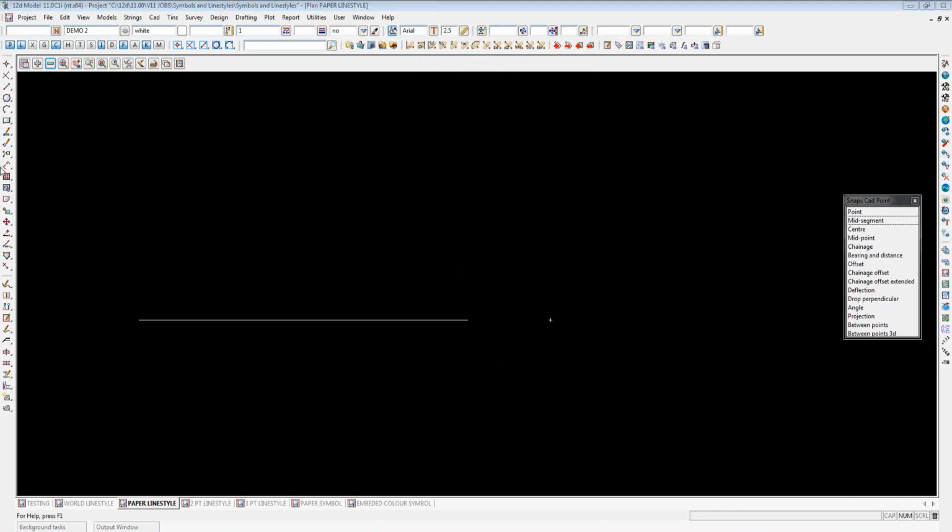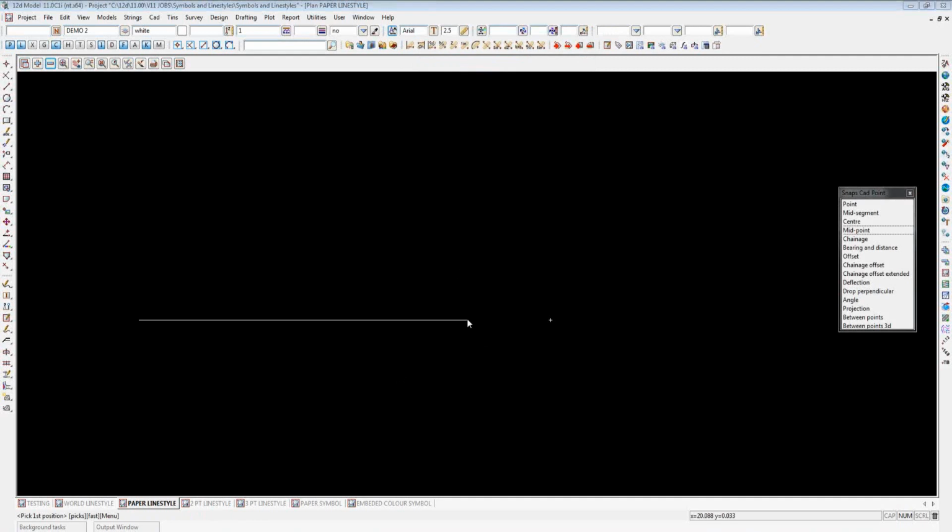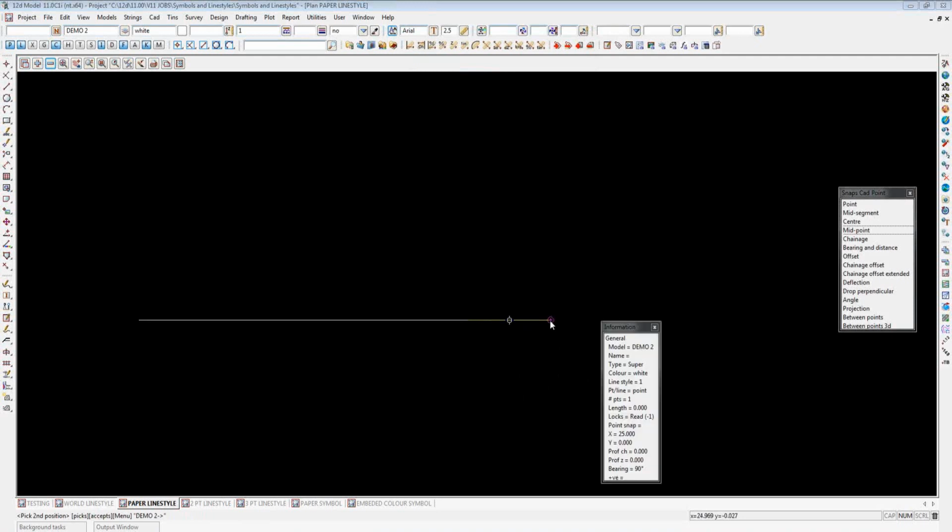So now I can create a piece of text. So on my CAD toolbar, there's create, pick position. Now on my snaps CAD, I can use the midpoint, which enables me to pick this point and accept. Then wherever I drag, it finds the middle point of that. Pick that point and accept.